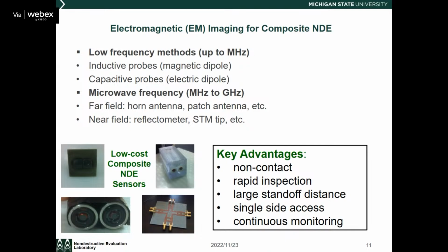Those four sensors are in-house manufactured at Michigan State, so we can design our sensor. Either it's inductive, which is shown here. This is an inductive probe. We have a two-coil sensor. It can be capacitive. This is an open plate capacitive sensor, a miniaturized sensor. You can also have microwave. This is a 6-port microwave measurement that you can have working in the near field.